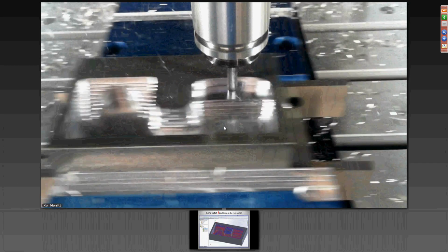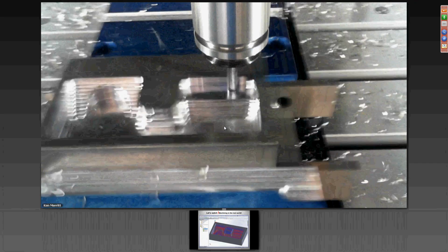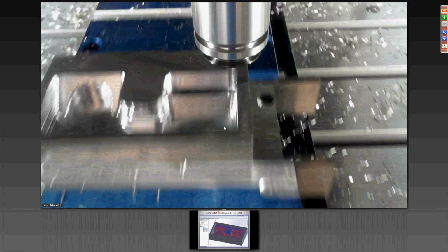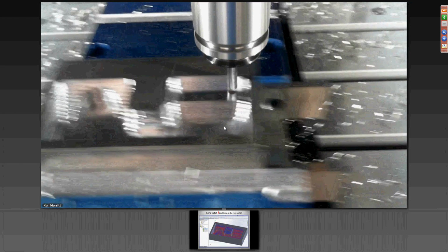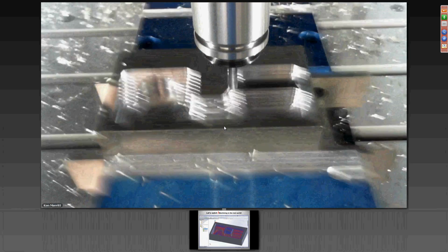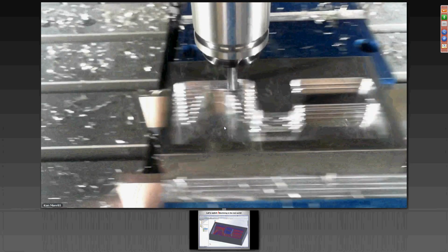So what we're doing again now is staircasing, and it's doing a little bit of flat leveling in some shelf areas, but notice that we start at the bottom and we work our way up to the top so that we can take advantage of the work that we've already done at the deeper cuts. And this optimizes the amount of material removal within a specific amount of time.